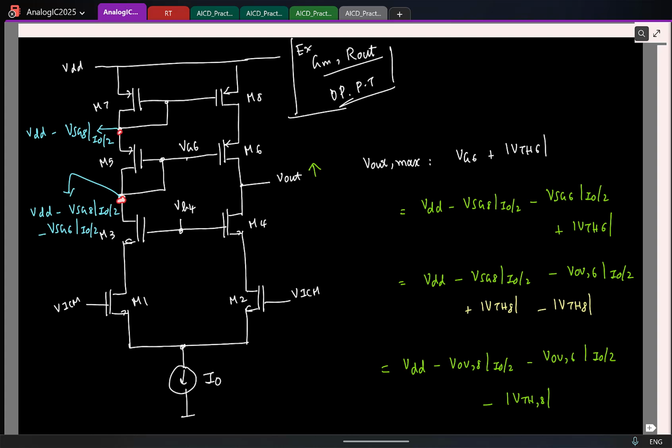This one. Yeah. This voltage is okay. I mean this is same as the source voltage for M5, and this is basically source to gate of M6. So this voltage is basically the source voltage minus source to gate of M6. So that's why you can't randomly say that, hey, this max I can goes VDD minus 2 overdrive voltage. That is not correct. That can happen if you have independent control on the gate voltage, because the fundamental limit is basically the fundamental battle is between gate and drain. Right? Max drain can go here is one threshold above the gate. That's it.